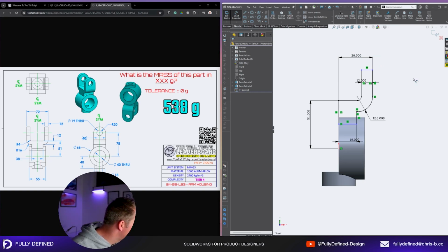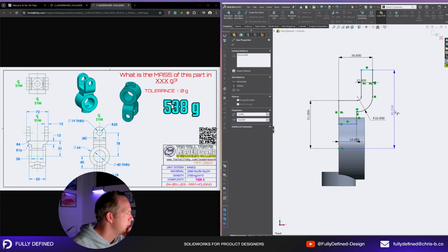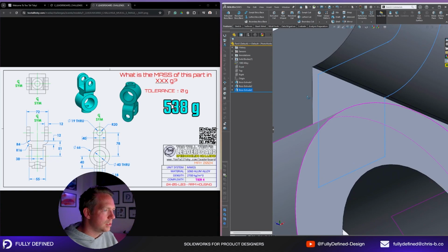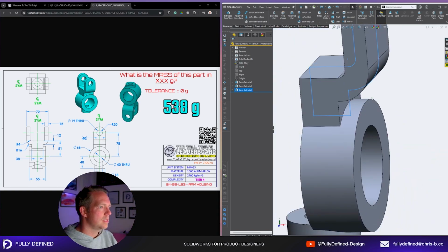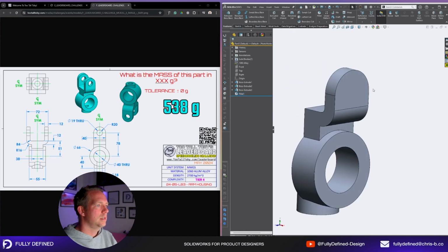Oh, there's a hole in the side, and that full face fillet. So I did this one around here, and that makes it fun because this dimension to the top doesn't actually go to the top. It goes to there plus another 10, so it's 88. This will be mid-plane. Already so 20, 40. You can see I've just covered the bottom. Just enough. Yeah, full round fillet, right, done.